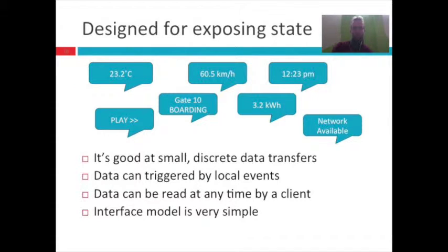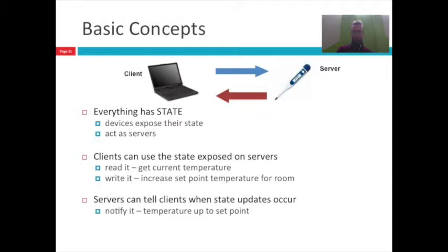Now, as I said before, Bluetooth Low Energy has been designed for exposing state. It is therefore good at small, discrete data transfers, like for example data from a sensor. Data can be triggered by local events, and data can be read at any time by a client. And the interface model is very, very simple. Some basic concepts.